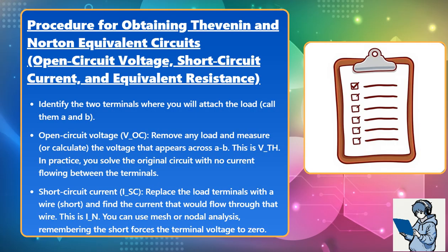Short circuit current ISC: replace the load terminals with a wire short and find the current that would flow through that wire. This is IN. You can use mesh or nodal analysis, remembering the short forces the terminal voltage to zero.